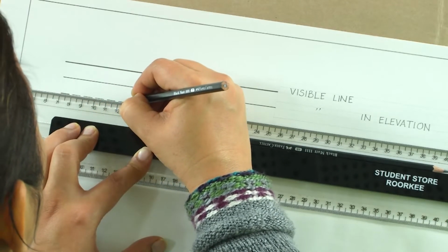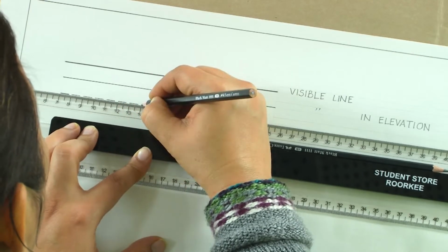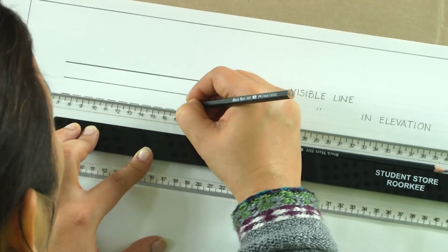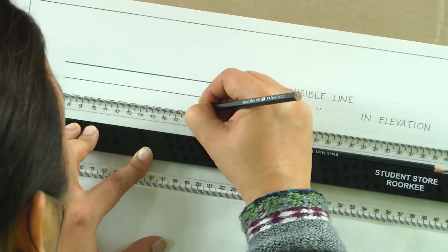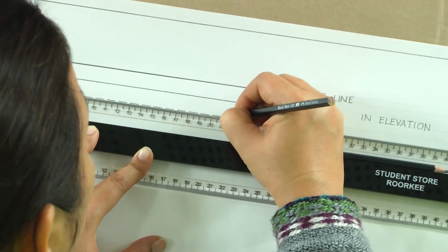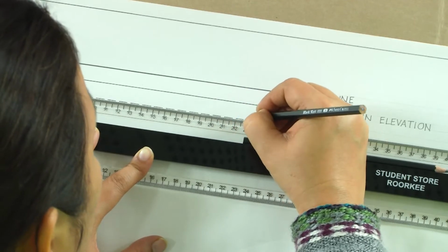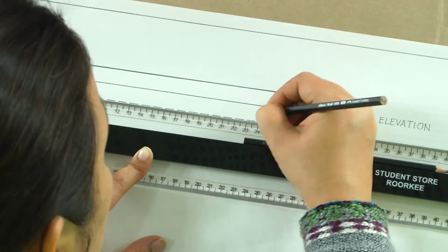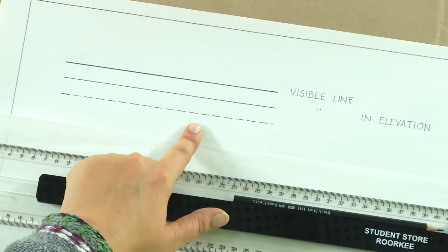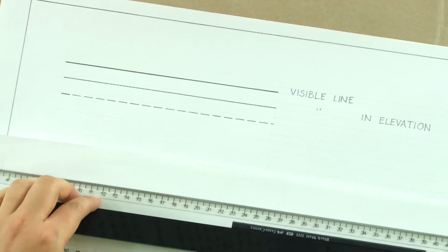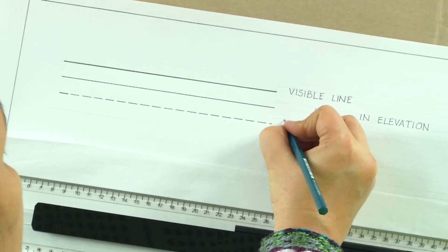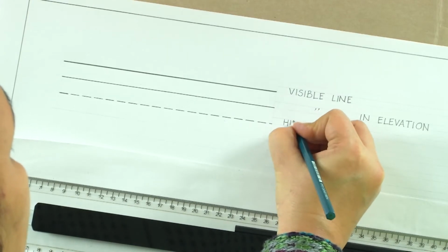This is again a thin and dark line. So, there is darkness in it, but it is relatively thin as compared to the visible line in section. So, if you draw for architects, if you are drawing a staircase, the steps of the staircase on the first floor will actually be seen in this line, which is the hidden line, and it is also called the dotted line. So, here we will use the nomenclature as hidden line.